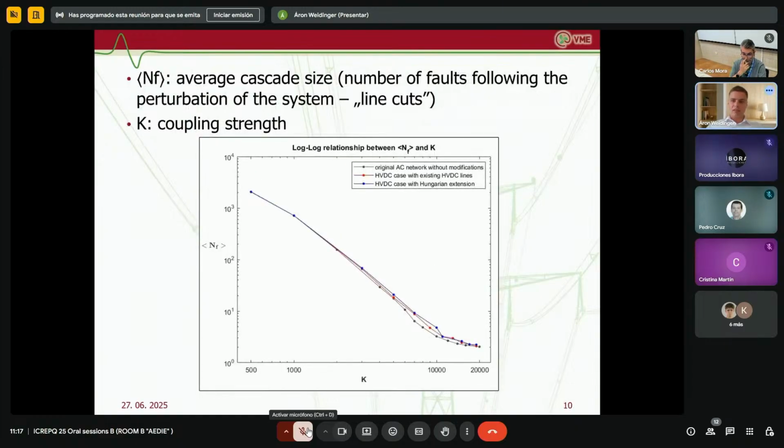In our final test, we simulated cascading failures. After reaching steady state, we randomly removed a power line to simulate a fault. And if the surrounding lines then exceeded a power threshold, they were removed as well, simulating a domino effect, so to say.